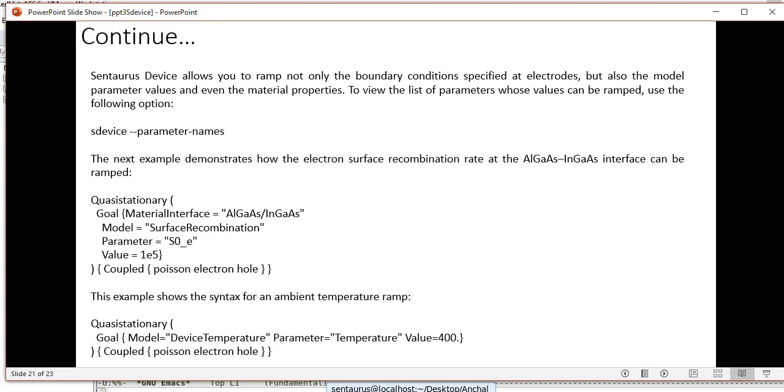So yes, the solve section is a little bit confusing, or you can say a little bit tough section as compared to the other sections, because here we have to keep the hierarchy in mind, like minimum step, initial step, maximum step, and this section also turns out to cause convergence problems. So we have to study this section very carefully if we want a smooth simulation.